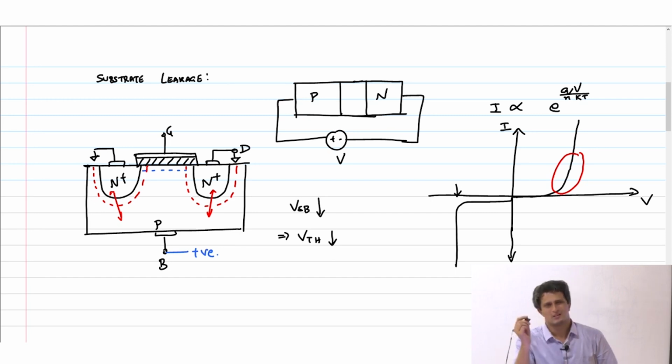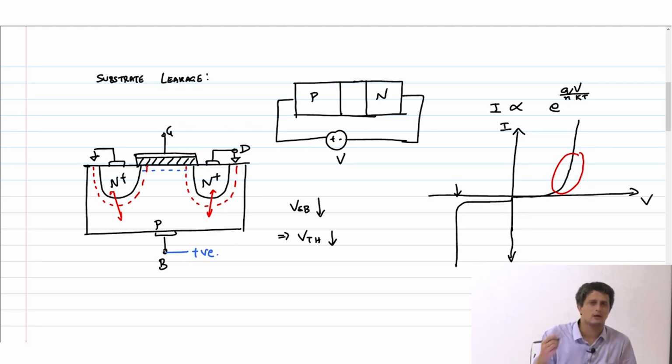And therefore, if you are slightly increasing it, maybe 10 millivolt, 20 millivolt, maybe even 100 millivolt, sort of okay, but be prepared for the extra leakage that is going to come about. Of course, you cannot take it to 200 millivolts, 300 millivolts. Then the leakage will be uncontrollable after that, right? So you don't want to forward bias any junction in the transistor, okay? Rather, I should say you should beware of forward biasing any junction in the transistor, okay? So that's the right thing to say.